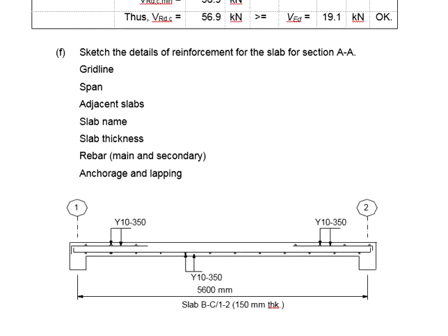Next, we deal with the reinforcement bar. There are main reinforcement and secondary reinforcement. The main reinforcement will be put at the bottom layer in order to have a higher effective depth. As for the secondary reinforcement, they are put on top of the main reinforcement bar in the transverse directions.